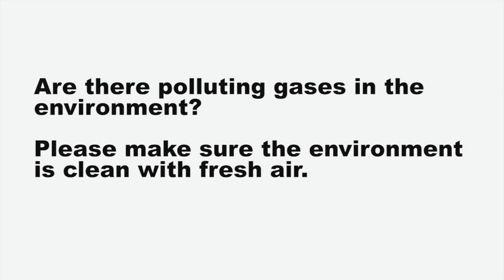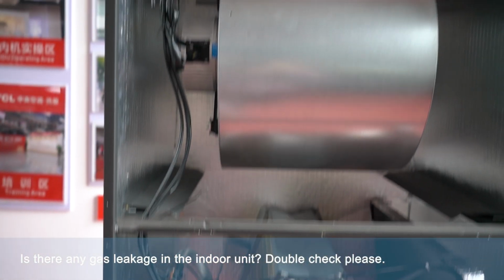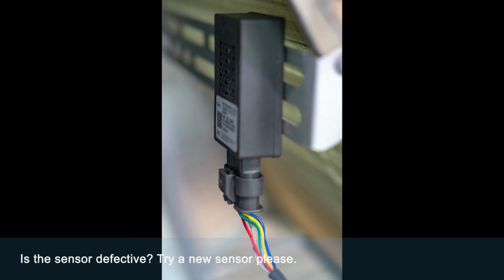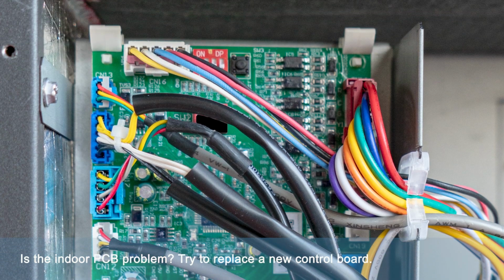Are there polluting gases in the environment? Please make sure the environment is clean with fresh air. Is there any gas leakage in the indoor unit? Double check please. Is the sensor defective? Try a new sensor please. Is it an indoor PCB problem? Try to replace with a new control board.